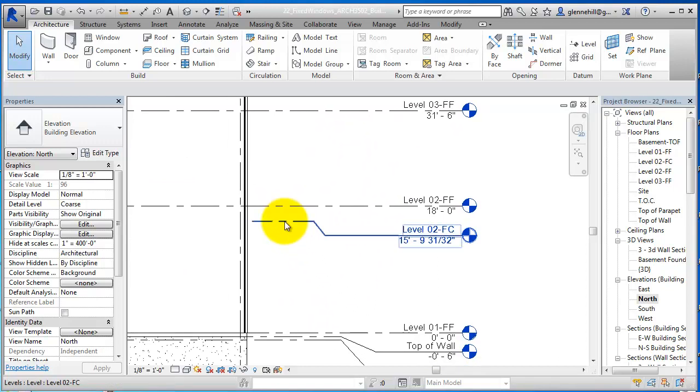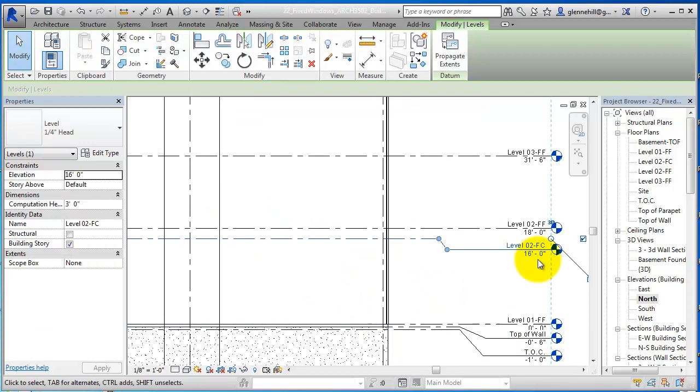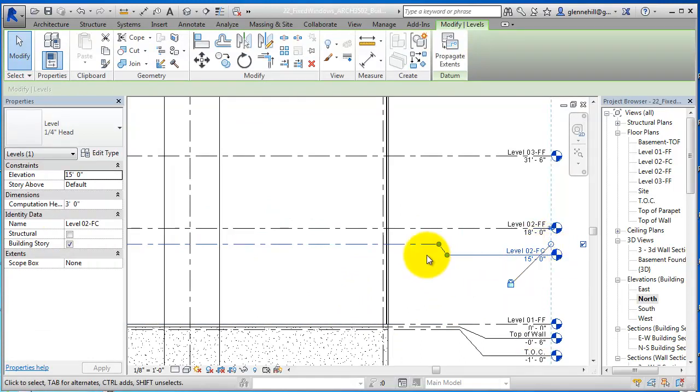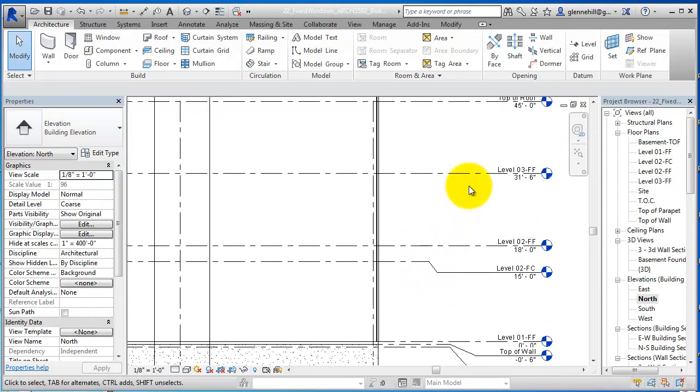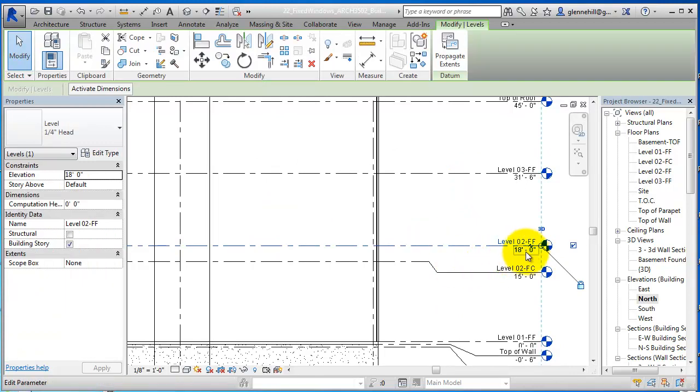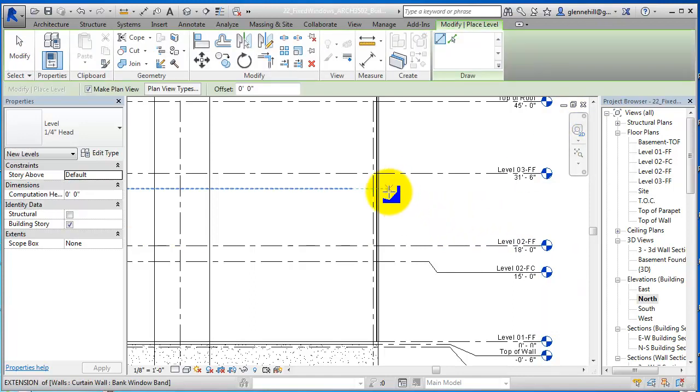But here I'm going to set the ceiling to 15 feet. So let's retype this as 15 feet. Give us 3 feet to work for mechanical and structural there. And then I'm going to put 10 feet in here. So I'm just going to add 10 feet to 18 feet. And let's go into levels again. Architecture levels.